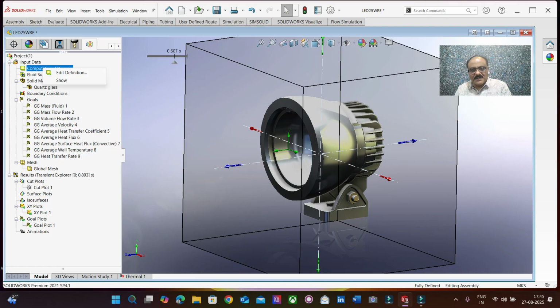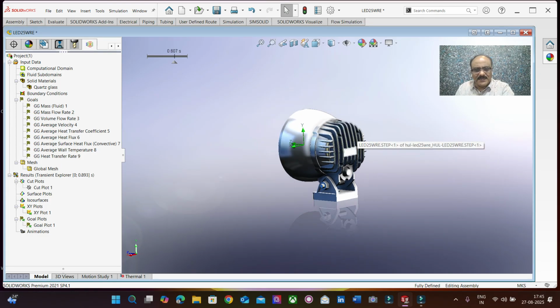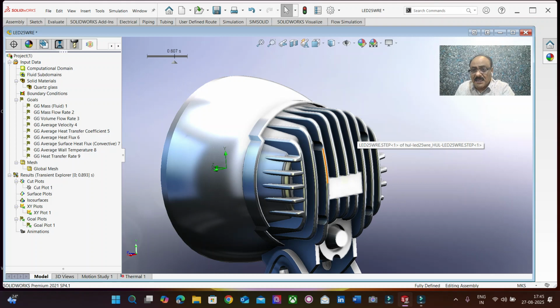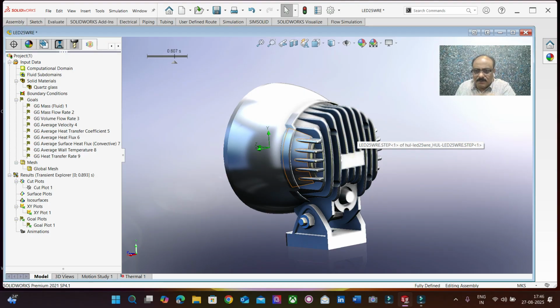At certain regions where I want to find the temperature across the thickness, or at some junctions where I need to refine, I adopt a narrow channel refinement process, which means the software has an intelligence in which I define that this particular boundary or this particular cell has to be further discretized, say about 10 times.